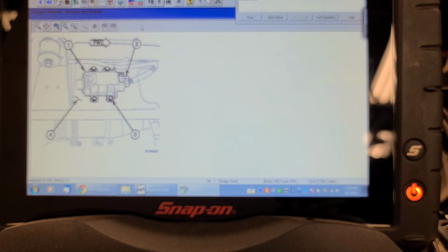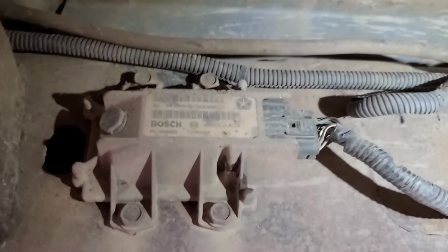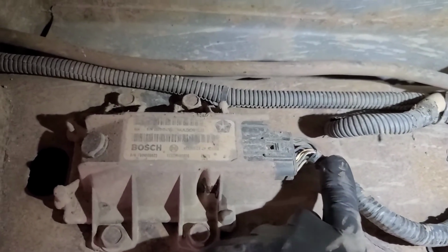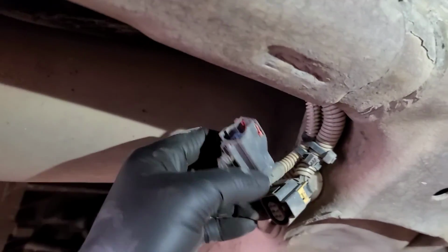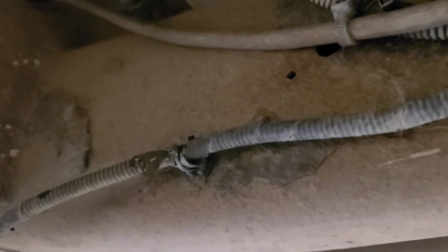So at least we're going to put it up in the air. We still got it on the hoist. We'll have a look at that and see if there's anything obviously wrong with that connector or the wiring to it. If we can't find anything, I'm just going to tell them to watch for that fuse to blow again. And it's technically supposed to be a 10 amp fuse, not a 15. So we'll talk to them about it. So that ignition feed wire is one of these ones coming in here at this oxygen sensor module. But everything has been disabled here, disconnected. Connectors for the sensors have been eliminated.